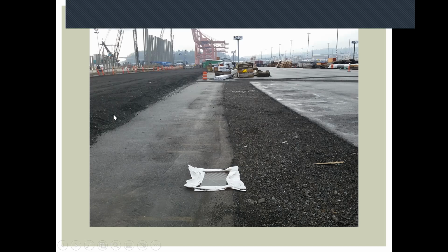And this one is really an example of a good thing. So utilities are going in at some point. The contractor ground up the asphalt but left it in place, and it allows water to infiltrate. This is a live storm system. It's going into somebody else's storm system, which they're regulated for their discharges. So we can't have anything going in. So it's completely blocked at the grate, and then overflow is going back into the ground to the right. So good thing.